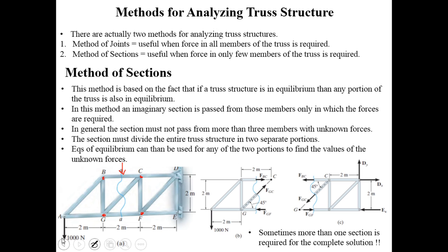So you see that here the only external load of 1000 Newton that is acting at point A is applied at the joint. It is not applied at any other location like this. Otherwise, this would violate the assumptions of truss structure. And therefore each and every member, since it is pin connected at both the ends, is a two force member, and so there is only one force acting in the member, along the axis of the member itself, the line joining the 2 points, if you remember the definition of the two force member. So these points are important to remember before starting the analysis of truss.